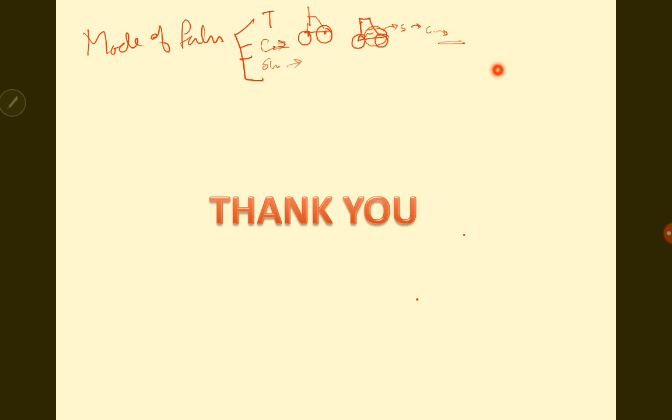Sliding can basically come under a material property itself, because we are just checking that the horizontal forces are well within the limit of mu into sigma V, where mu is the coefficient of friction of the material. And then the last is overturning. In overturning, you have the overturning and disturbing moments, and it can be either in the heel direction or in the toe direction based on the forces that act. It's basically a force analysis in case of overturning. It can be with respect to the heel in case the horizontal forces are in the upstream direction, or there's an earthquake and the forces are in the upstream direction. In that case, the overturning can be with respect to the heel part.